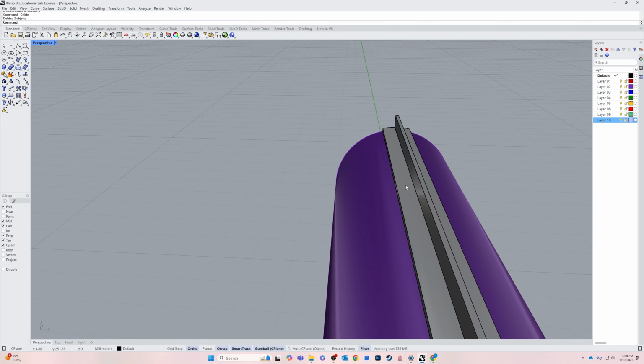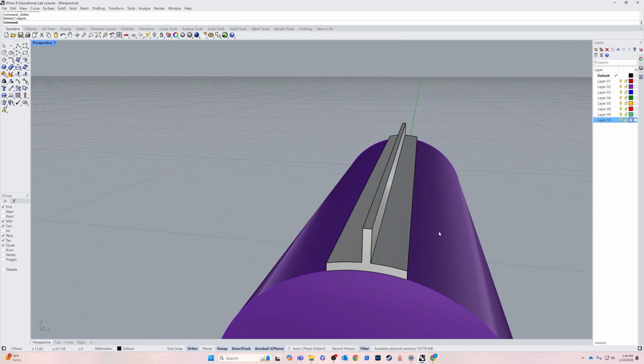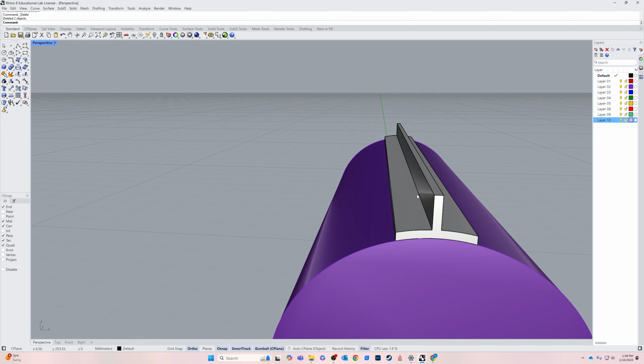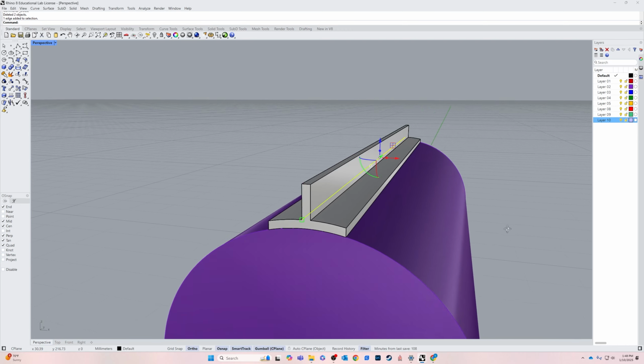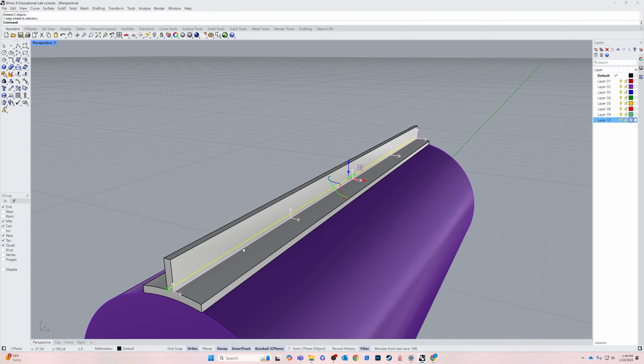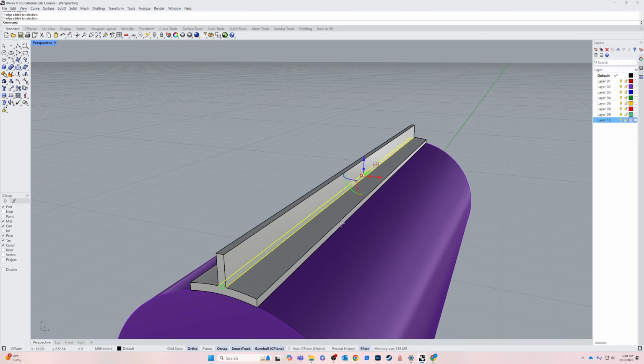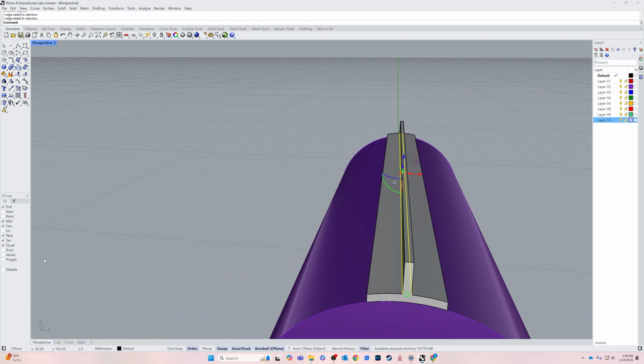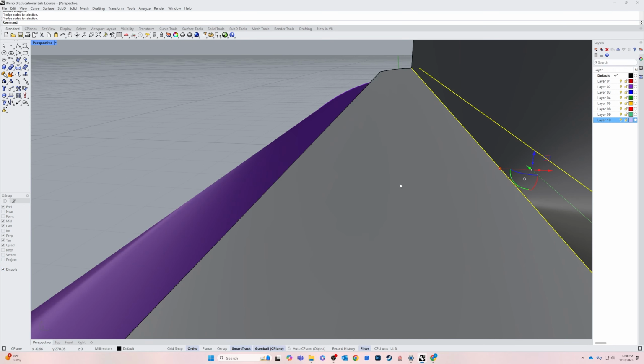All right, so next we want to change the shape of this to match our kind of triangular looking bevel here. So I'm going to Control-Shift click on this section, Polysurface Edge, Control-Shift click, or Command-Shift if you have a Mac, Polysurface Edge. And then I'm going to go ahead and disable my snaps. Make sure you don't have grid snap or anything random turned on.